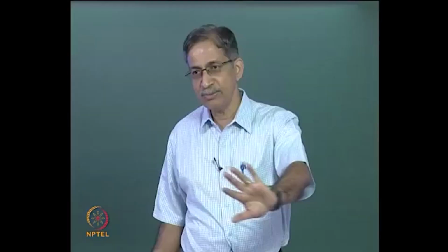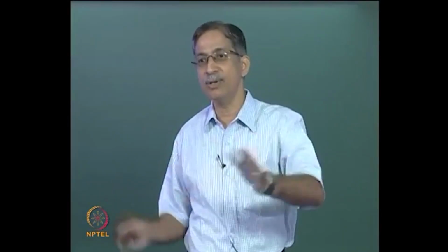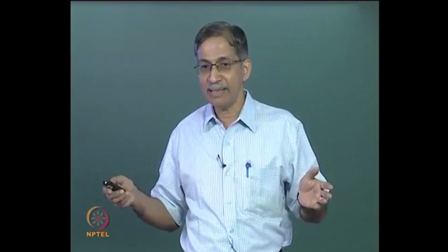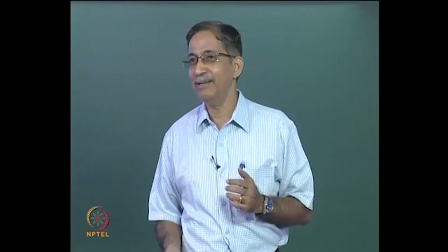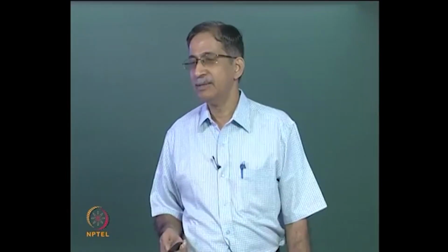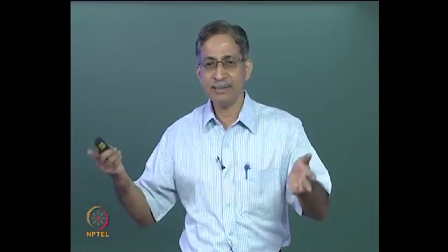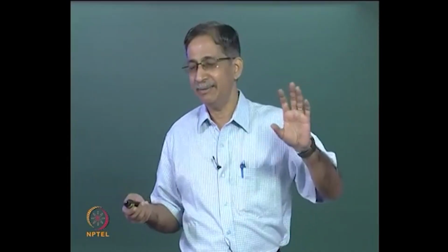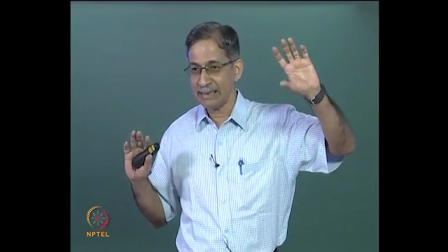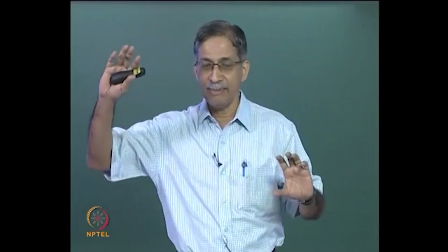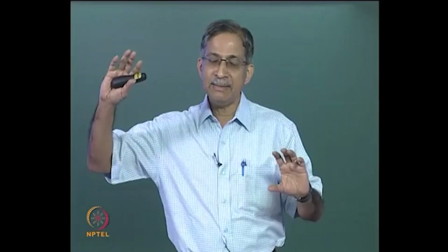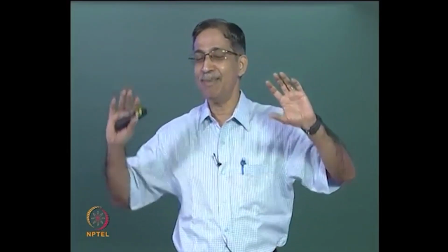So what is the next step? You have got the transformation matrix, you have got the fixed end forces, you have got the net loads, you are ready to solve the compatibility equation, but you need something. You need first, before structure, the element, and then you have to build. So we go to the flexibility matrix. So the element flexibility matrix, what is the matrix for a prismatic element? Just so that your memory is okay, L by 3EI is the diagonal, and the off diagonal is minus L by 6EI, that is it. So you do that. You can do it in one shot, you have got the F star matrix, is it clear?